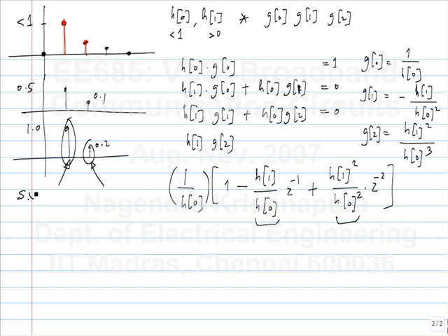The signal to noise ratio that appears in the bit error formulas, basically Q of SNR is the bit error ratio. That is the ratio of signal to the random noise, not this ISI. The signal to ISI will not give you this one. Okay. This is the signal to ratio of that noise which is Gaussian distributed with an infinitely long tail. That's what gives you this formula. No, it won't, it's not very precise to say that.